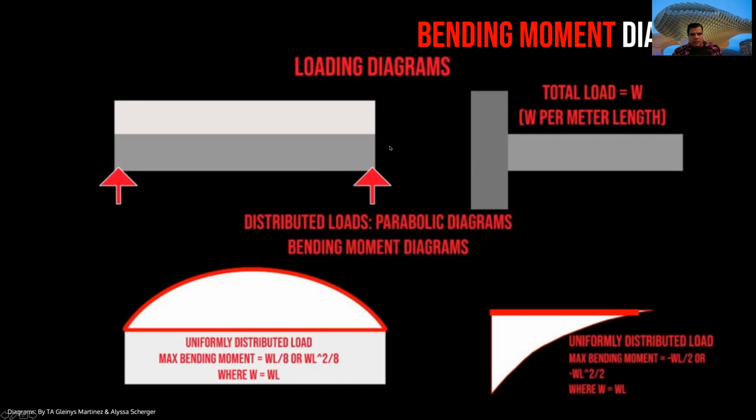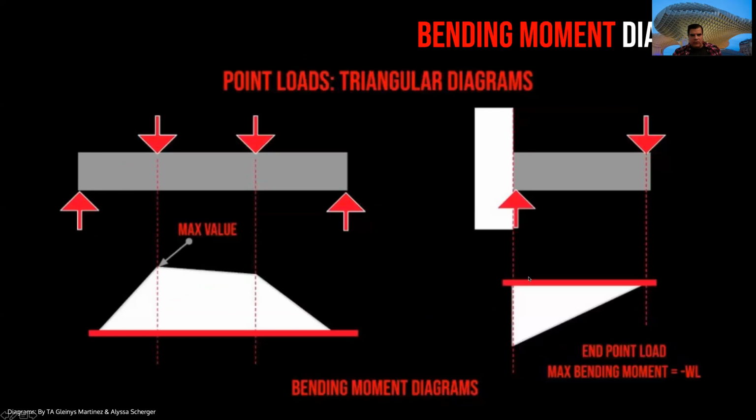When you have a distributed force, because of the type of deformation that the beam has, we say that the moment will be curved. That is something that maybe you will not understand as a theory, but I think that looking at the diagrams, you will be able to do it. The important thing is that when we have the bending moments, we want to know the maximum value. As you can see in this example, the maximum value in the curve is the tallest number here.